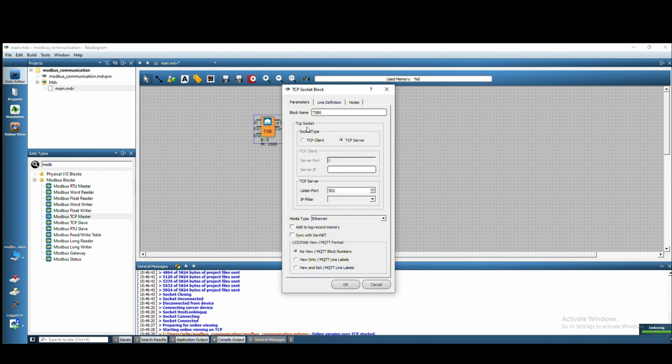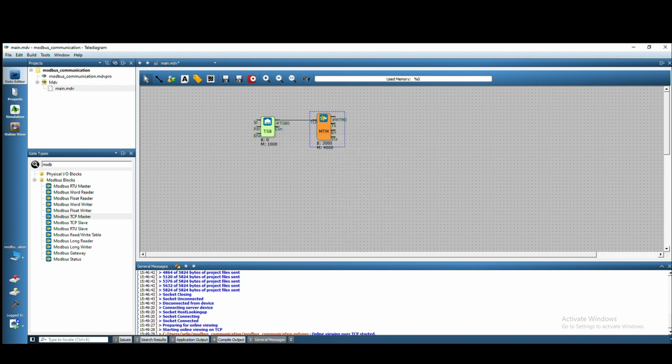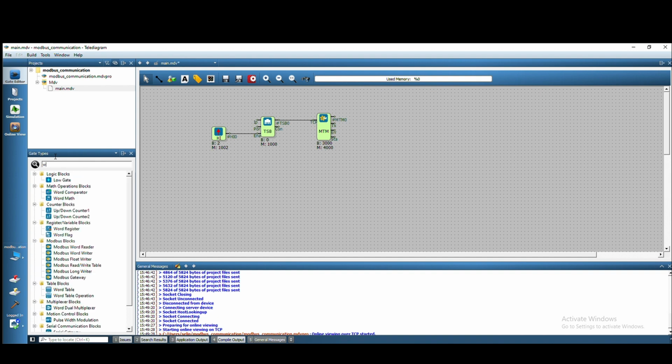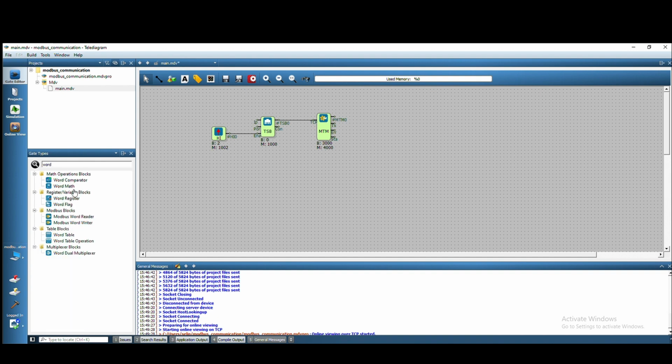First, we open the server port as a TCP client through the MODBUS_slave program. The server port is defined as 555. The PLC can open 3 sockets. An edge-triggered input must enter the TCP socket block's enable input because you can open multiple sockets at the same time, allowing you to connect simultaneously.